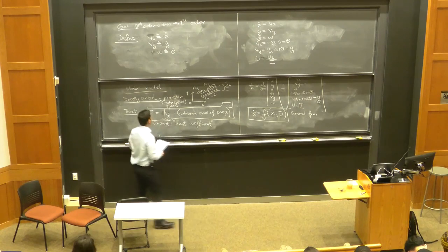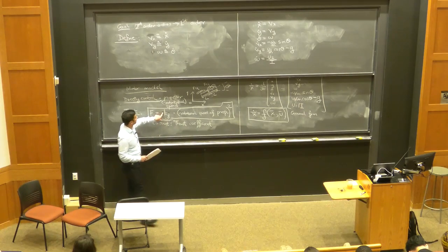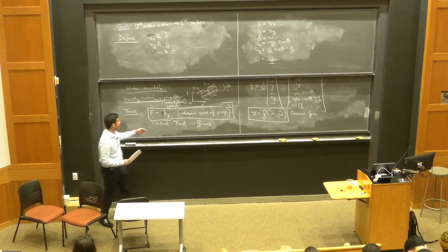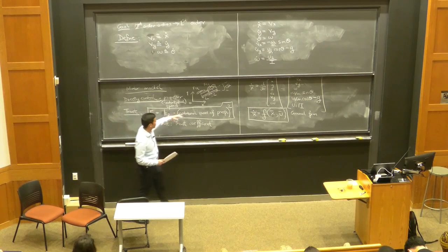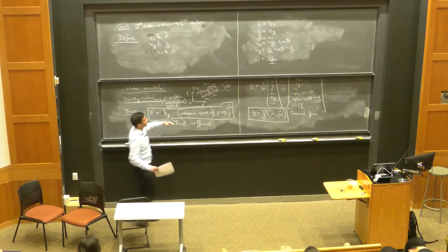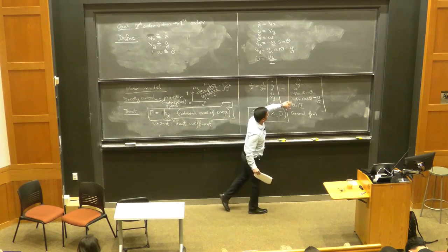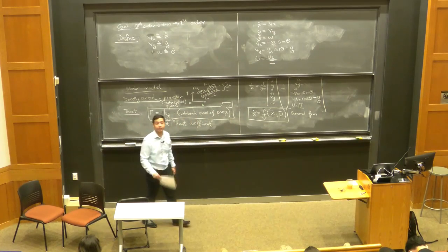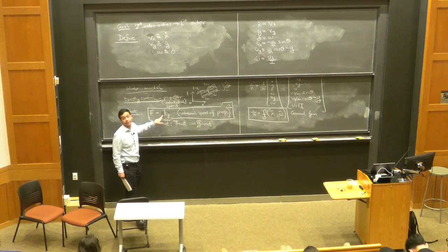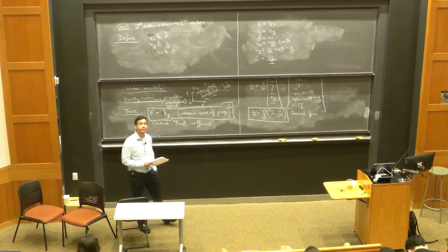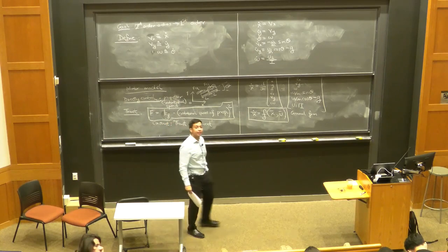So, all right, let's think about a question: how can we measure what this thrust coefficient is? That's important. What we're really controlling is not directly the thrust force. You get to control the rotational speed of the propeller. But our equations of motion, the dynamics, involve F1 and F2 through U1 and U2 over here. So if we actually care about predicting the motion of the drone or controlling the drone, we need to know what the thrust coefficient Kf is for our particular propeller, for our particular drone. Does someone have ideas for how one might go about measuring this empirically? Go ahead at the back here.